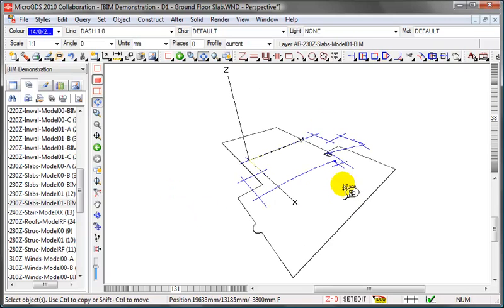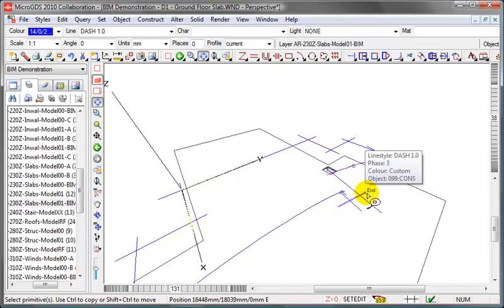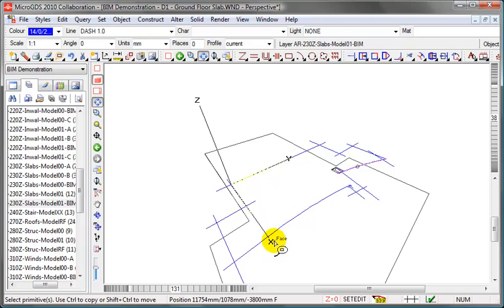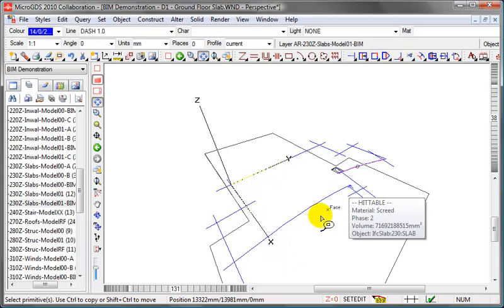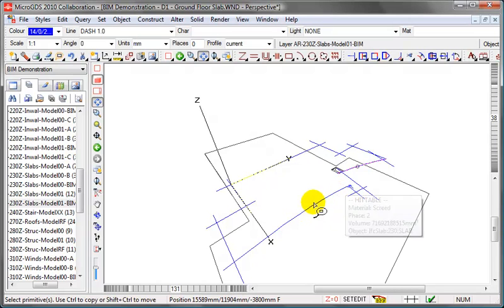And just one observation for you, the graphics here, these curved graphics which are the wide radius curve, as for the ground floor internal walls that we created in an earlier video. I've created these as an arc, but because they are very large radii and the faceting that MicroGDS applied would not be of fine enough resolution, I've used the alter facet command to add the facets to the line itself.